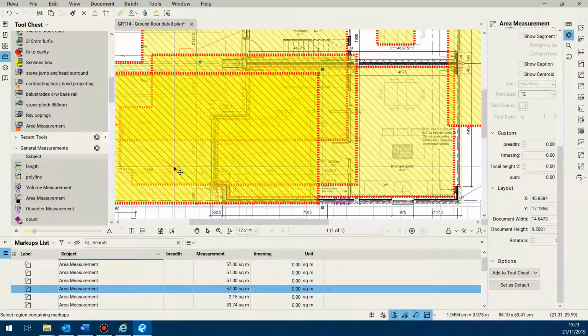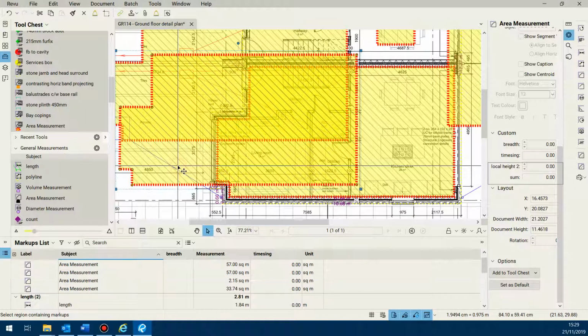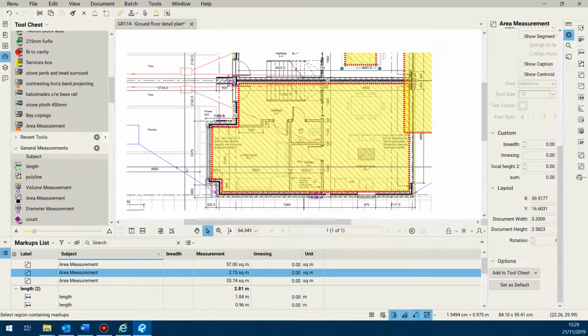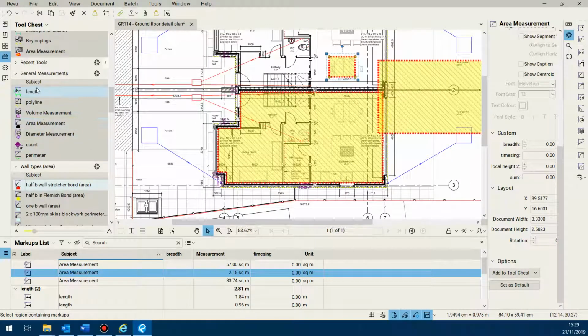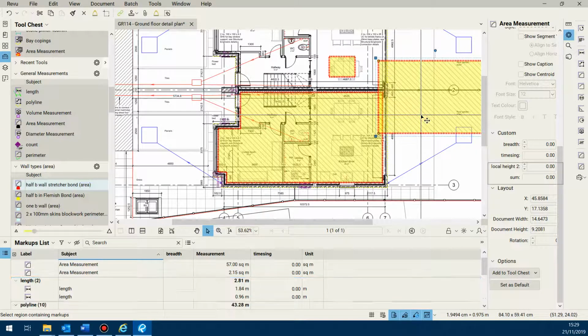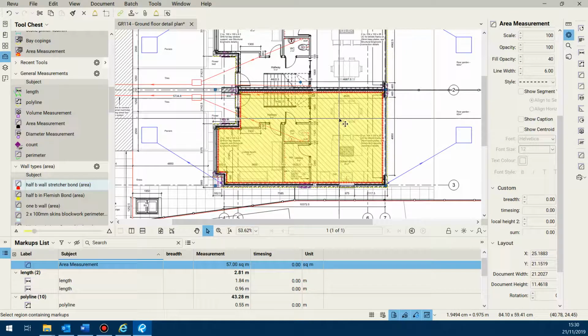It's quite important. So that's the main way of creating tools, and effectively what you're doing is you're preserving the original default tools of Bluebeam with their properties. You're cloning it and you're changing the newly created tool to use the properties of an area measurement or the properties of a polyline. Hopefully that makes sense. I'll answer any questions after this lesson if you need me to expand on that further. Let's just get rid of these other shapes. We'll get rid of that for now.